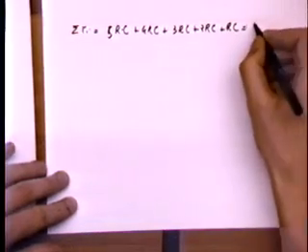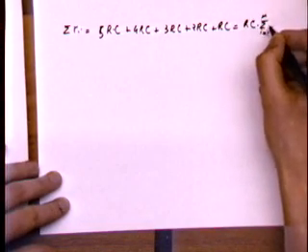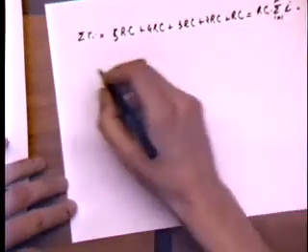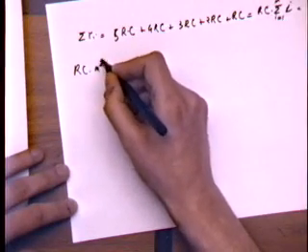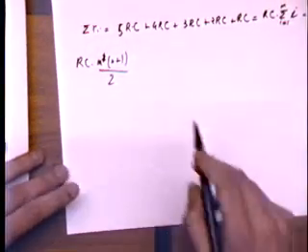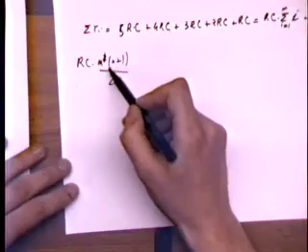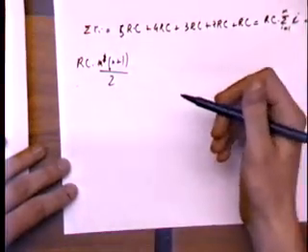In other words, it's also equal to RC times the sum from i equal to 1 to n of i, okay? And we know that this is equal to RC times n times (n plus 1) over 2, right? In other words, what we found is that if all capacitors were equal, we would have a quadratic dependence of the tp on the number of inputs, okay?